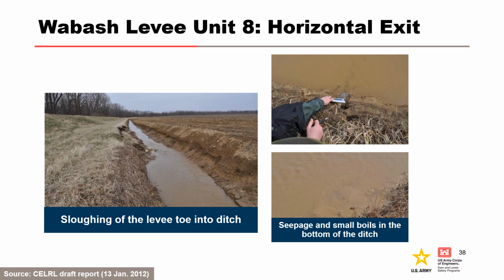The gradations from Wabash Levee Unit 8 were discussed previously. A farmer dug a ditch at the landside levee toe to help drain a farm field, creating a horizontal seepage exit. The levee ultimately breached. Sand boils will be discussed in the following section.